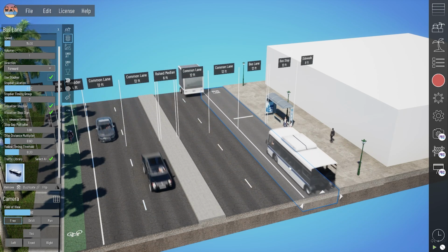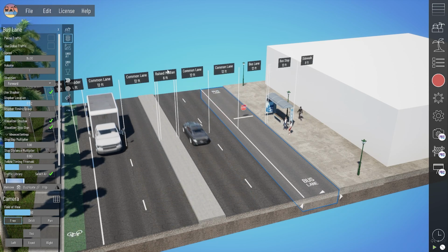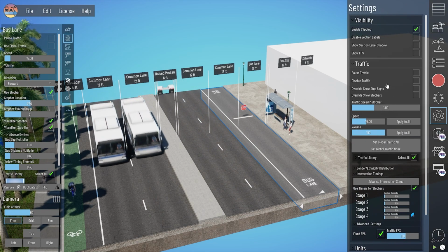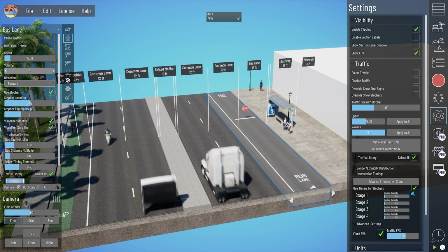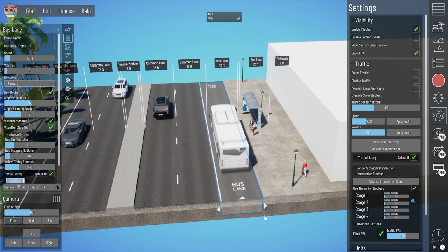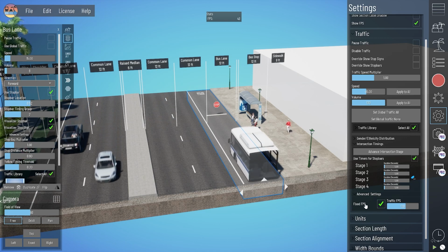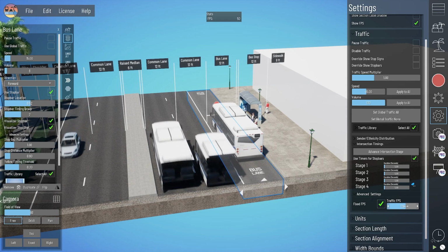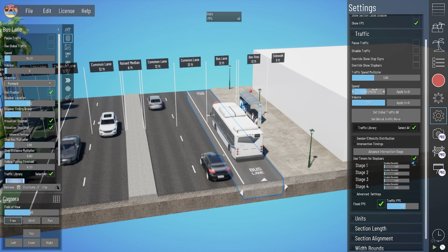But for now, I think the best way to control your traffic is just playing with some of the settings. It's dependent on the speed of traffic. It's dependent on the volume. It's also dependent on your frame rate. Traffic is spawning when you have a volume greater than 1. It's spawning based on the frames that your Beyond Typicals application is running. That's why down here in our global traffic settings, we've got this fixed frame rate so that the traffic will all be predictable and come in at a set rate that isn't dependent on the performance of your computer.